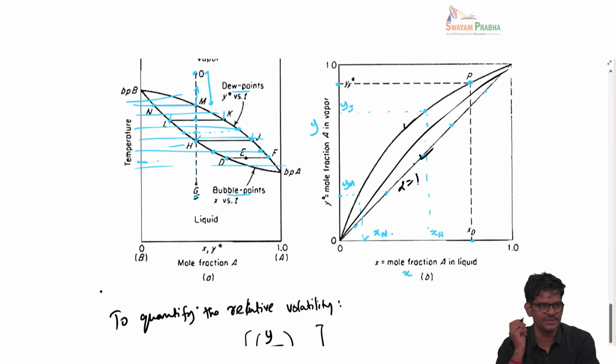For any real system where one component is more volatile than the other, you will see alpha greater than 1. If you make alpha larger than 1, it's better. Okay, because for every partial evaporation you are enriching the gas more than the liquid easily.